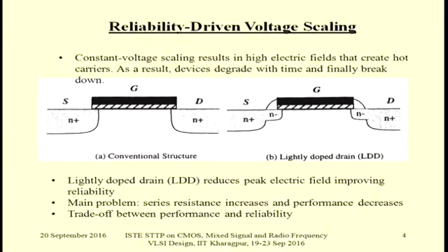So we have to think of design reuse. As far as design reuse is concerned, it is better that certain components, like the input-output drivers, stay. The internal elements which are performing the actual logic computation can be changed with the advent of CMOS and scaling down of the CMOS. You can change the power supply, but the input-output voltage drivers play an important role while you connect subsystems. So constant voltage scaling is very important. This is very much in vogue.